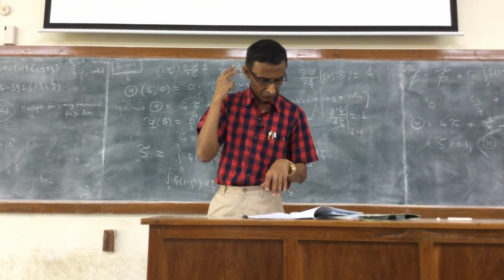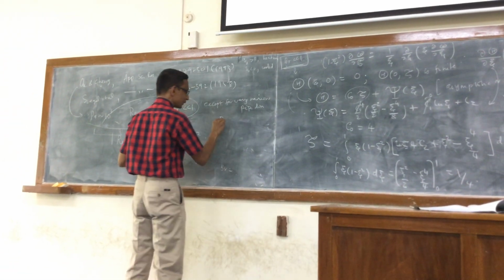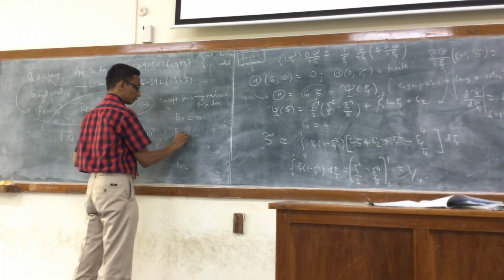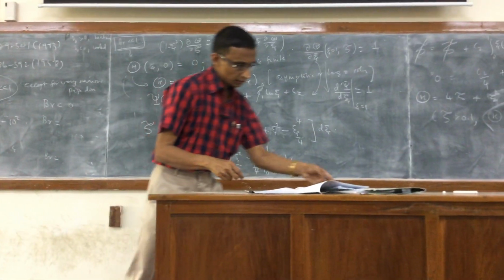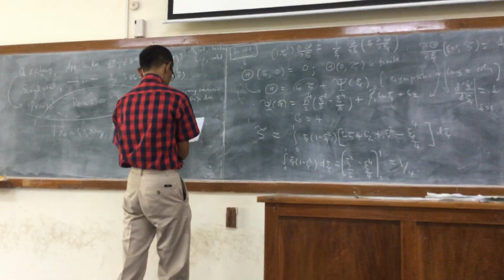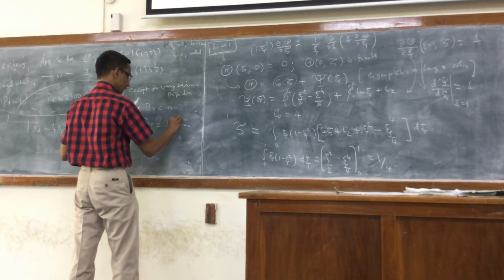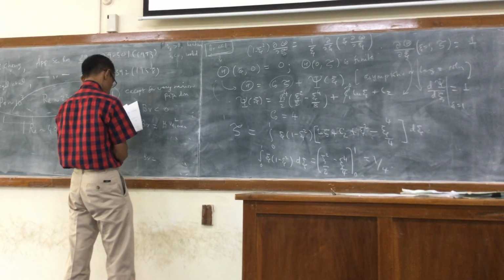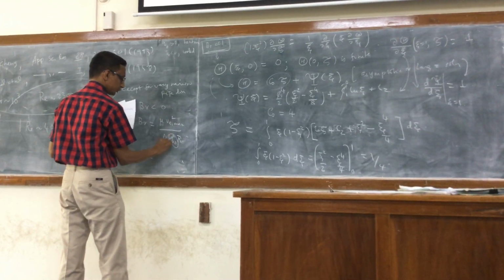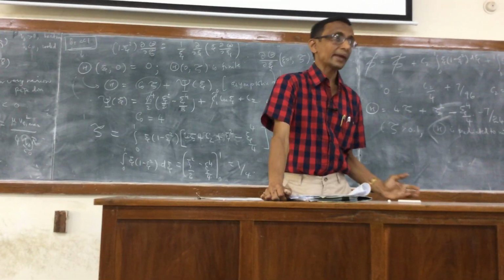The interesting situation pointed out is what happens when the Brinkman number is actually less than 0. So if you look at the Brinkman number, it has this form, so how can it be less than 0? It can be if you're looking at cooling. So if Q0 is less than 0, then the Brinkman number will be negative.